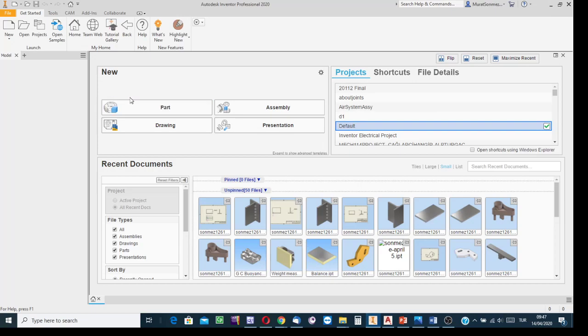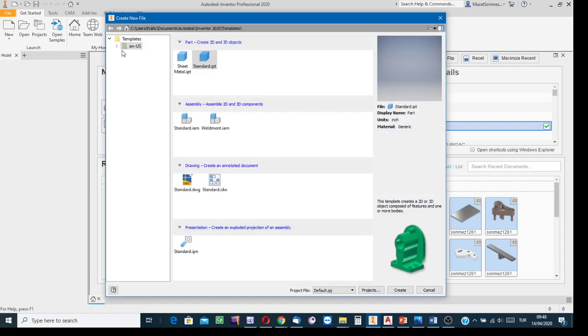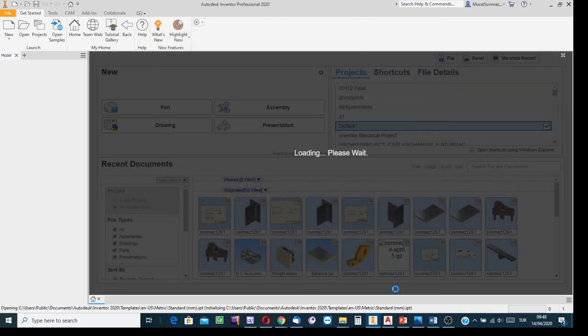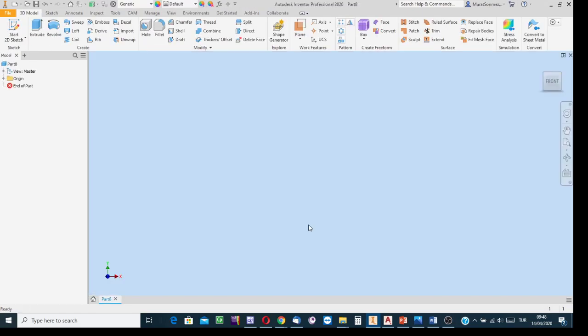And then open Inventor. And then since it is going to be a new creation, logically obvious, click on the New File Creation button. And in this dialog box, you know quite well the things to do. Select the unit of measurement and then make the selection on this template for single components. For creating the model of a single component, that is the template to select if you already selected the metric unit system. Okay, and then click on the Create button. Yes, here is the 3D environment, the Inventor environment.